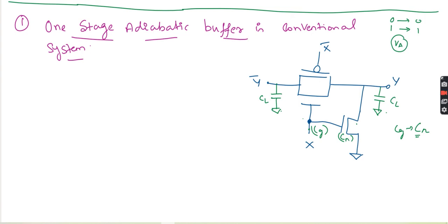Right? So now, very important thing in your circuits, normal, conventional CMOS circuits and all, there will be much more power dissipation in the internal node capacitance than the load capacitance, because the internal node capacitances are more. But your CL, that load capacitance, always will be very large compared to the internal node capacitance, always. So always your CL will be very much greater than CI actually. So now first what we need to do here, we need to analyze. First let us analyze.